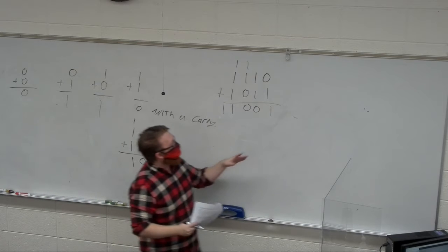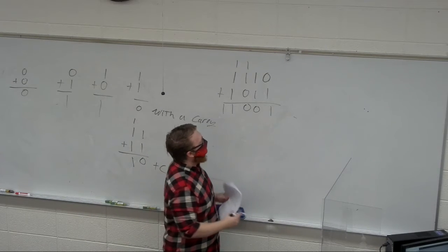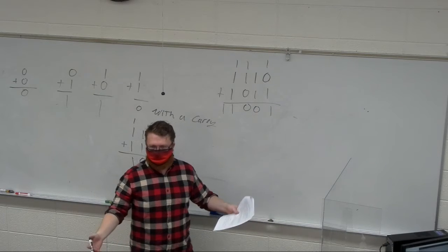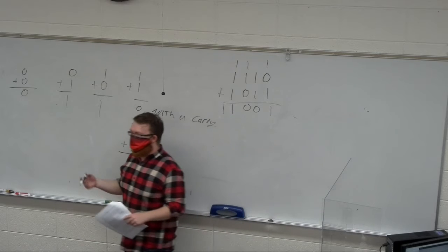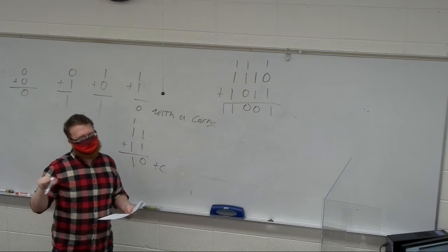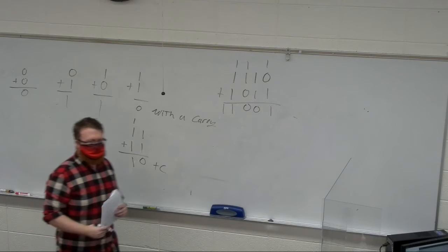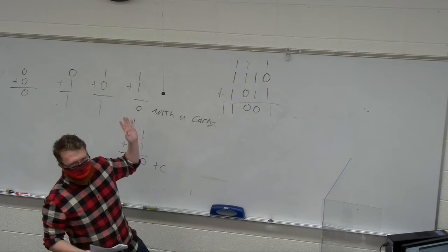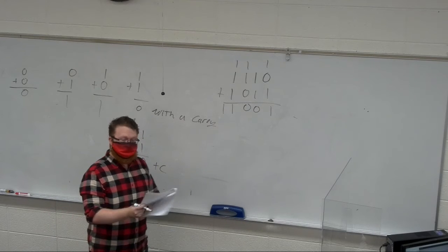Similarly, this may be the higher order bits of a larger number, and you may have a carry in, right? That is possible, to have a carry in and a carry out. And that's the nice thing. This is the fundamental idea of what we call a ripple carry adder, or ripple adder for short. And what they're just saying is it ripples along adding them all up. And we can build this into a circuit pretty easily. And look at how to do that.